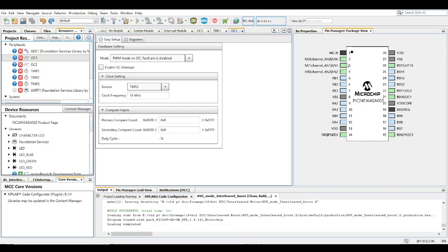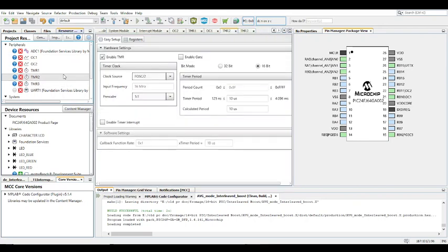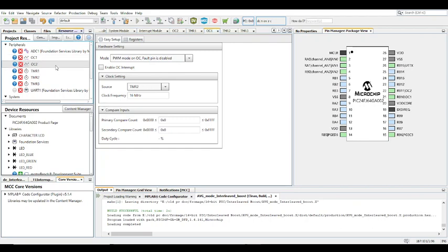Obviously here are the three sensors to be used: AN0, AN1, and AN2. AN0 is the output voltage sensor, AN1 is for the first inductor, and AN2 is for the second inductor. There are two MOSFETs being controlled, so two outputs are needed, OC1 and OC2, controlled by two different timers. The PWM has to be out of phase, and this controller does not have a feature to make it automatically out of phase, so you have to do it manually, which is done in this case. Output capture 1 is controlled by timer 2, and output capture 2 is controlled by timer 3.